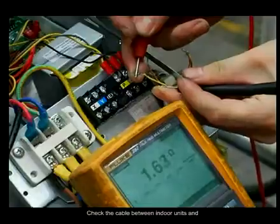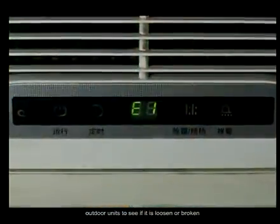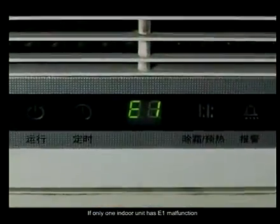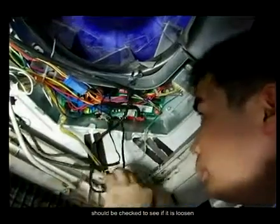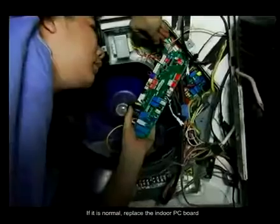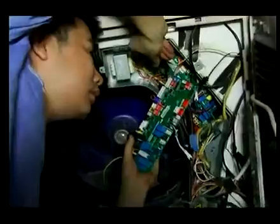Check the cable between indoor units and outdoor units to see if it is loosened or broken. If only one indoor unit has E1 malfunction, electric control cable and connection socket should be checked to see if it is loosened. If it is normal, replace the indoor PC board.